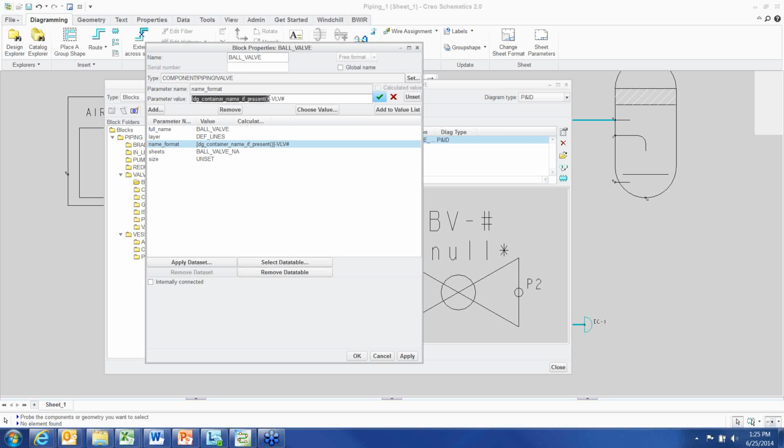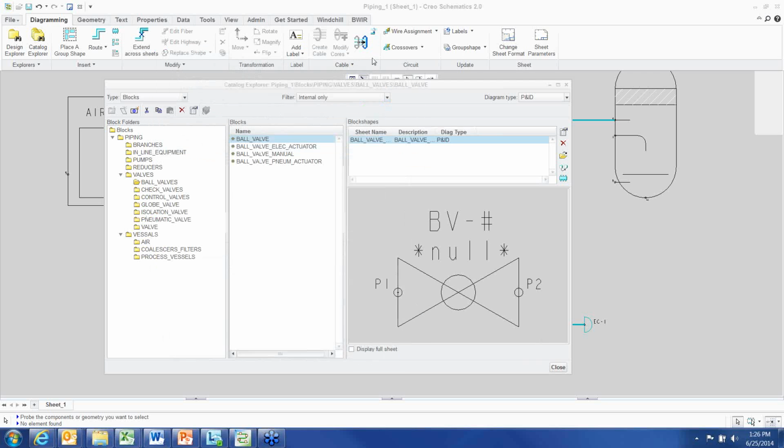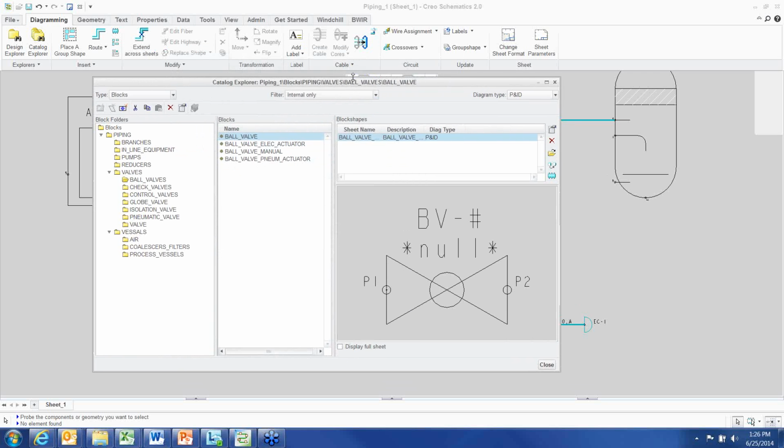They give this to you to go ahead and pull. It's a little Java call. It says if it's in a container, in this case a pipeline, give me that name first, dash the VLV and the pound, which means 1, 2, 3, 4. And so you can basically rehash these however you want into whatever kind of naming convention you want. So it's pretty powerful there.